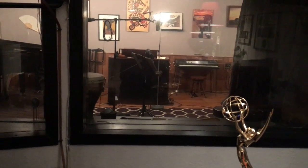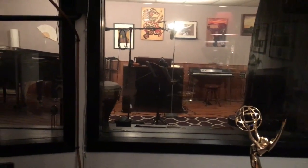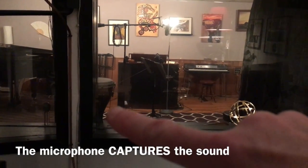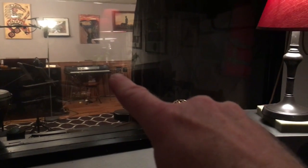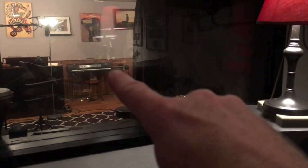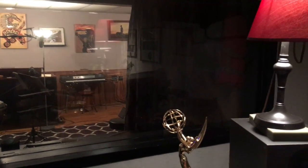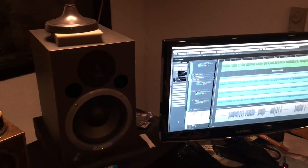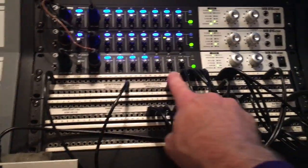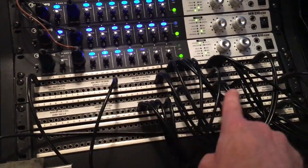So let's review. How does it work? Microphone into microphone power supply on the floor. From there, behind the organ, into the wall panel, into input number 1. From there it goes into a snake that goes up through the wall, across the ceiling, and drops down into the corner of the room, into a punch down panel that's located in a box underneath this mixer. That punch down box is connected into this patch bay, which allows me to route signals anywhere I want them to go.